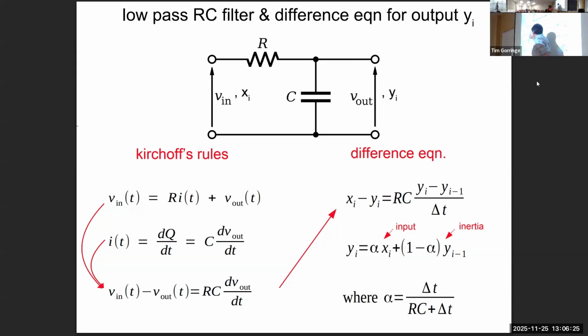What we wrote down here, the voltage across the resistor, I wrote it using Ohm's law as current times resistance, because I'm going to substitute in my understanding, again, for current law of what this current is. This current that's flowing through that resistor is the current that's charging up the capacitor.